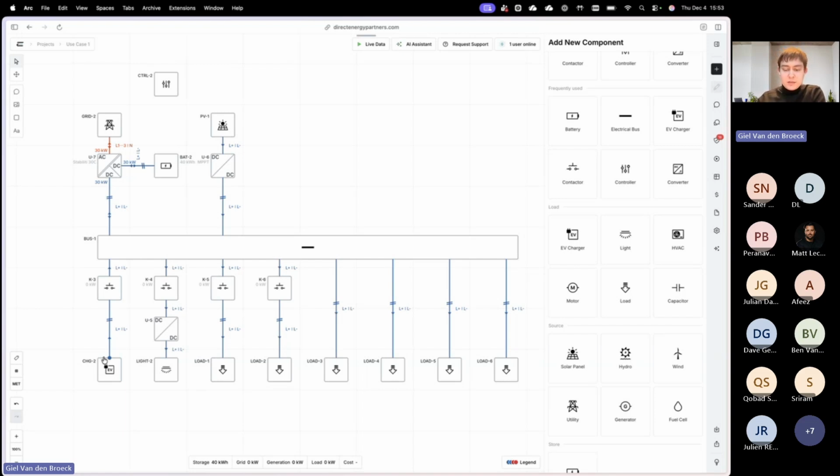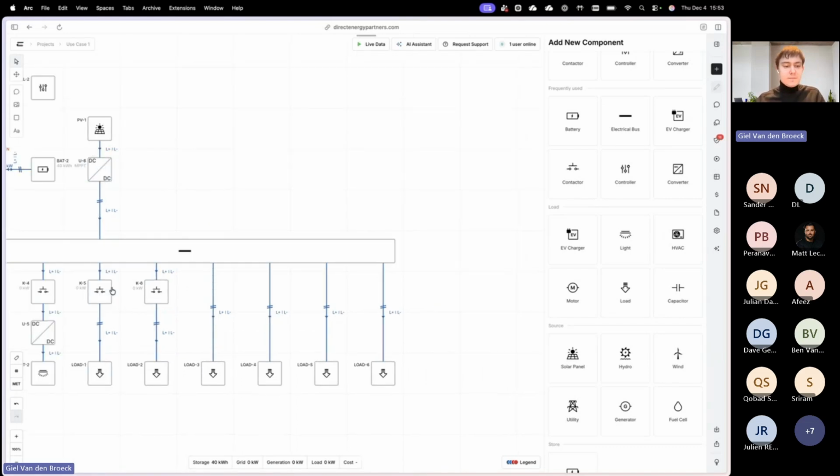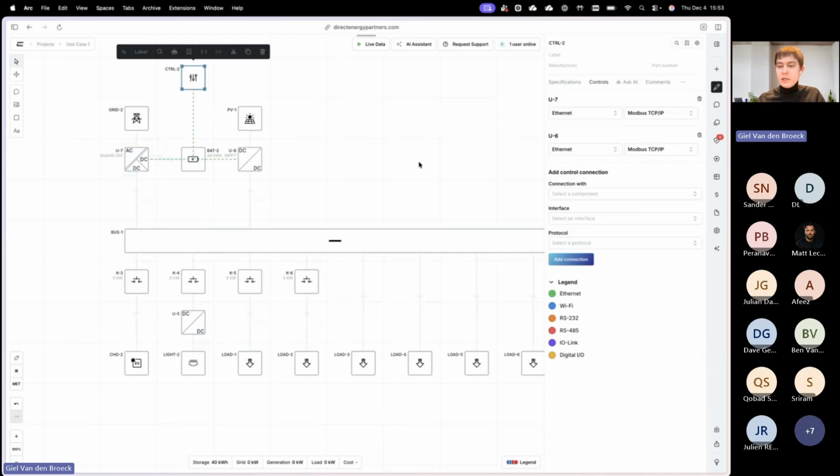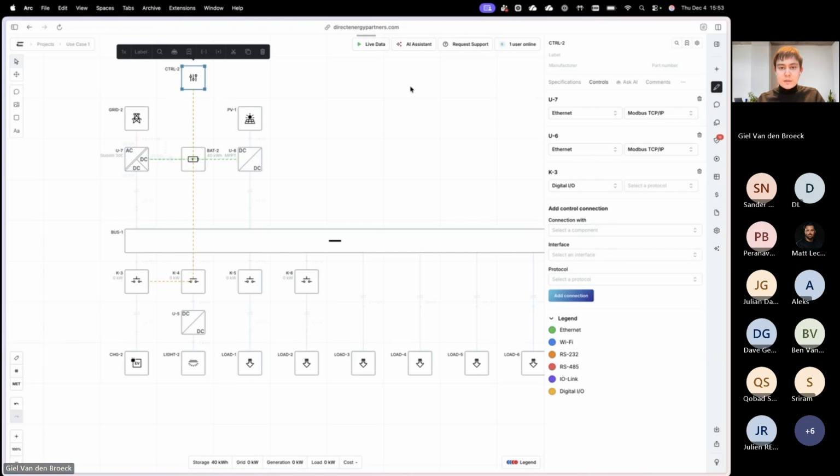So you start from 0 volt and you add capacitance on a DC bus. What will happen is you will have a large inrush current flowing from the DC bus to get these capacitors charged, and that's what you want to avoid. That's why you add pre-charge over here: to lower the ramp rate of the current, slow down the pre-charge, and control that process. So this controller was also communicating with those pre-charge contactors. These were just 24 volt auxiliary powers, so it's just digital I/O, adding it in here.